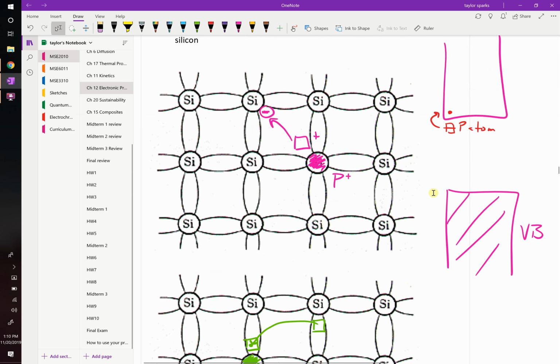It still takes a little bit of energy to make this happen, but it's on the other side. It's now down here. This was a hole for a boron atom. For each individual dopant, every boron that we put into the structure, we're putting a little tiny state right there, which is close to the valence band edge, which means if you've got an electron hanging out in the valence band, it can jump up and occupy that level. So now that level becomes occupied like that, and you create a hole in the valence band.